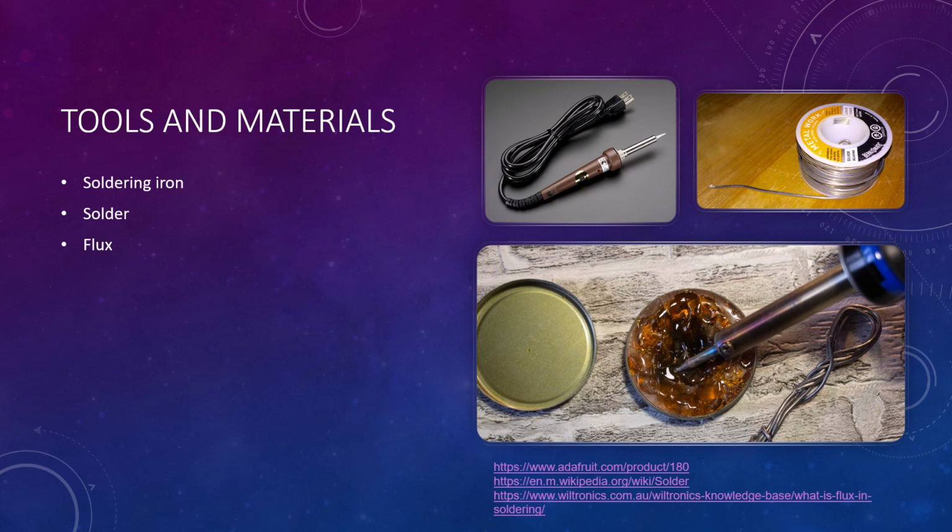Sometimes the part that is being soldered can have oil, dirt, or oxidation. The flux will help prevent oxidation and chemically clean the metal. The flux used is rosin flux, which helps with the mechanical strength and electrical contacts in the part.